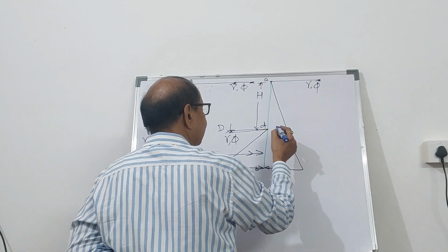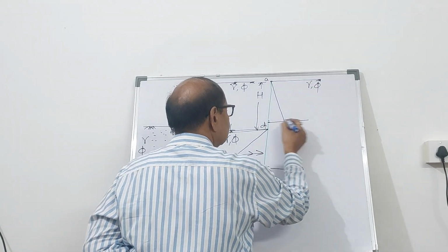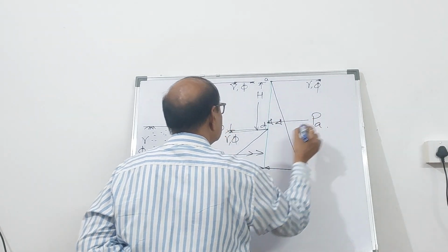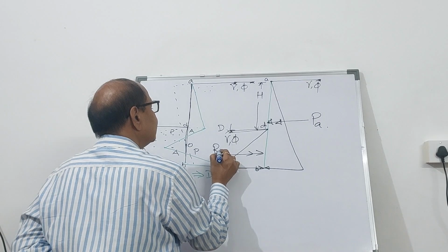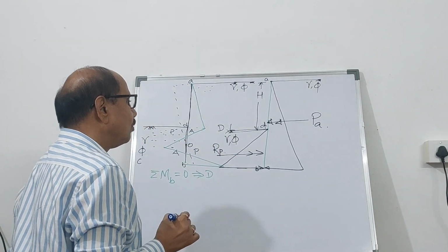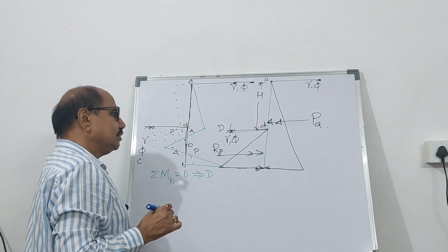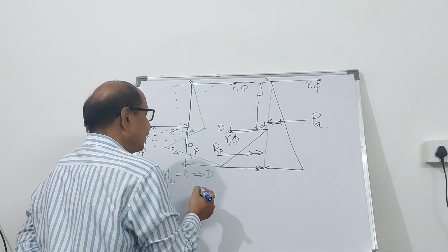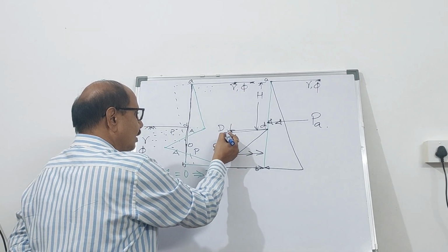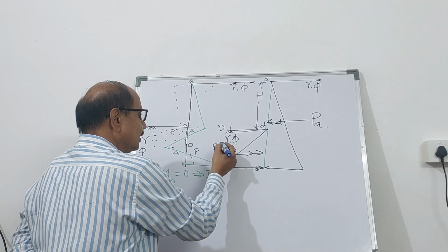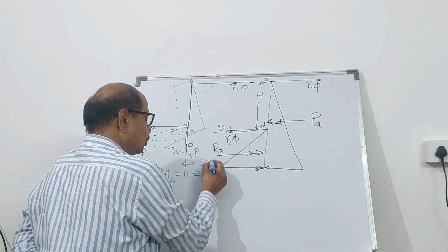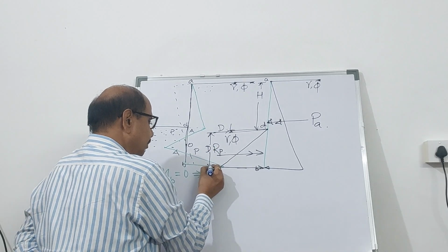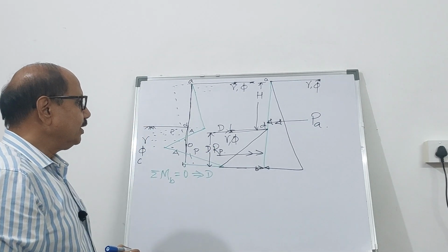So here it is going to be active, and this side, the resistance offered by the soil mass below the dredge line, we can take as RP. And from the dredge line up to the bottommost point, the depth of embedment, you know, is going to be D.